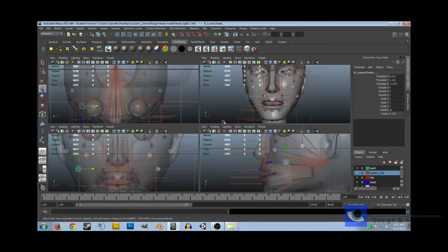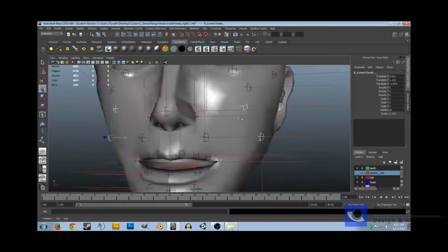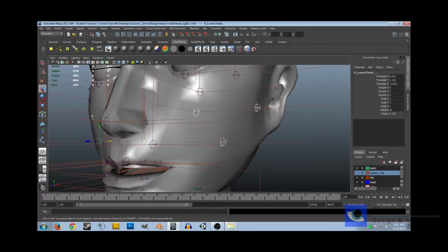Now create 3 joints for each cheek. The joint near the eye is for the muscle that moves up at a forward angle when the character smiles. The other cheek joint is for when the cheeks puff up, such as holding their breath, and also will move inward and outward as the character speaks. The one in the back should only be moved to enhance the look of, say, when the character holds their breath or has a look of anger when they pout.